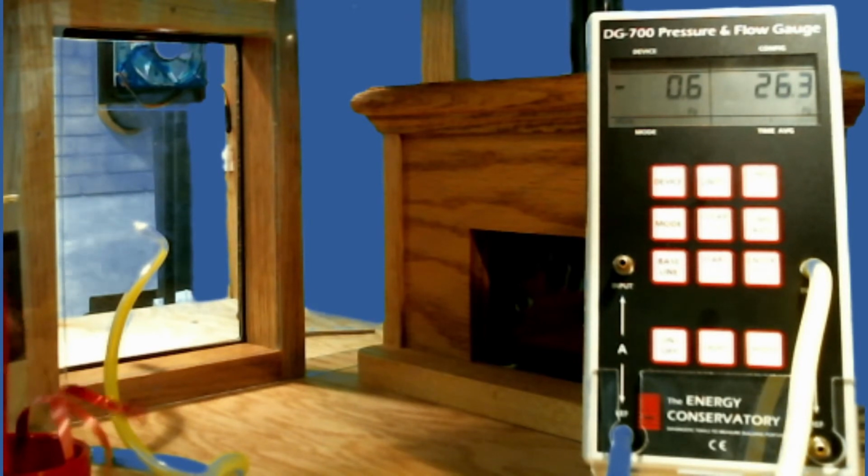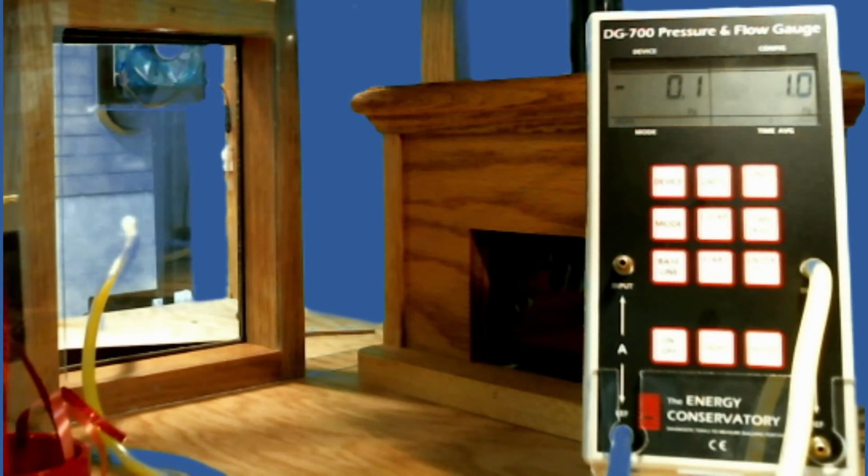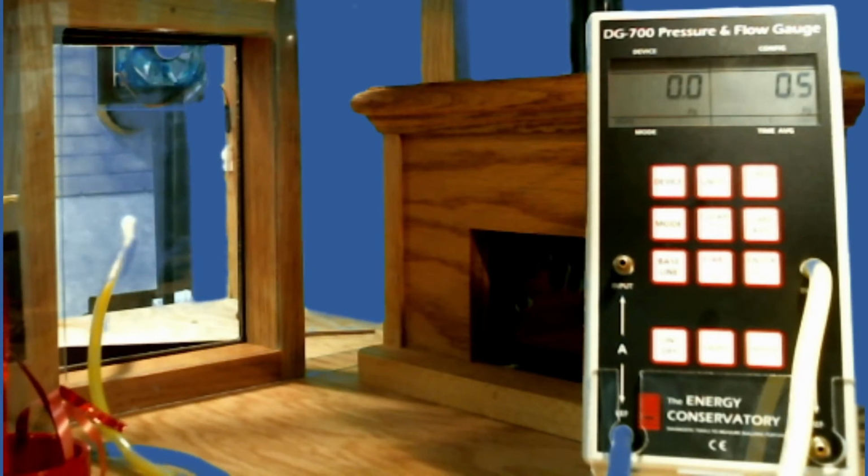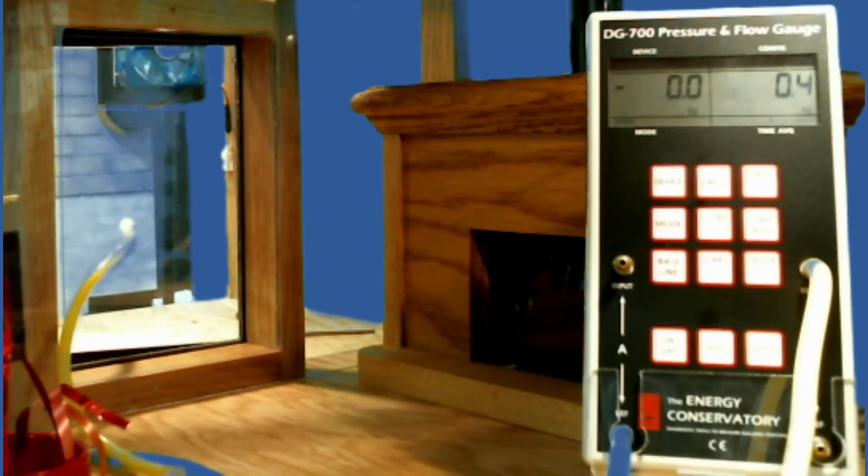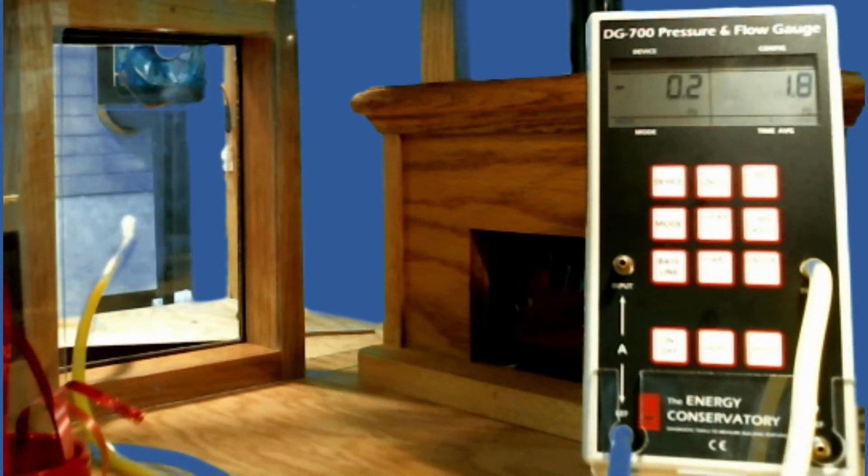And then what I'm going to do is open the bedroom door, and we'll see what happens. I'm sorry, the master bathroom. I'm going to open that. You can see me open it. And when I do that, just like on the bedroom door before, the pressure in the bedroom went down, and then the main body went down. So both of them kind of equalized.